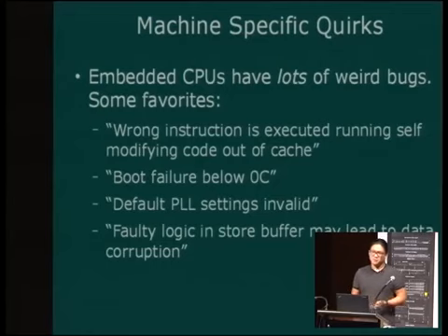You get weird stuff like boot failures below 0C. Fixed, don't run it cold. Okay, great. Another one is default PLL settings are invalid.